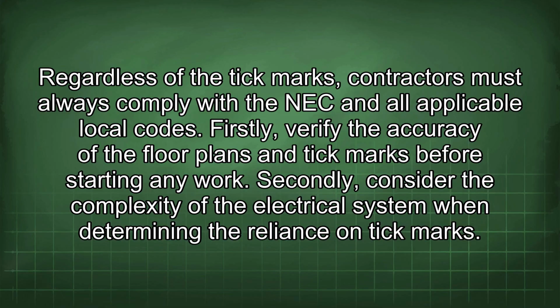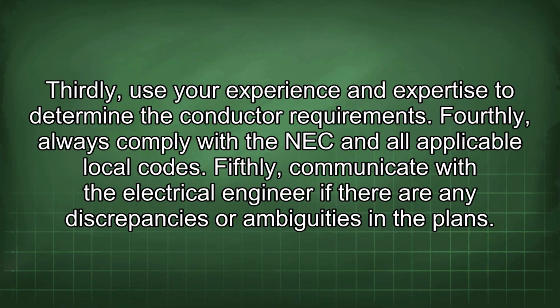Firstly, verify the accuracy of the floor plans and tick marks before starting any work. Secondly, consider the complexity of the electrical system when determining the reliance on tick marks. Thirdly, use your experience and expertise to determine the conductor requirements. Fourthly, always comply with the NEC and all applicable local codes. Fifthly, communicate with the electrical engineer if there are any discrepancies or ambiguities in the plans.